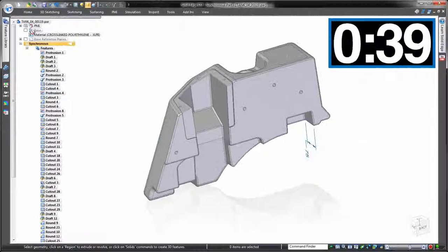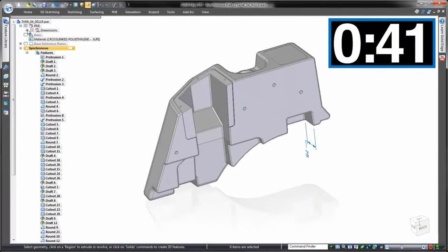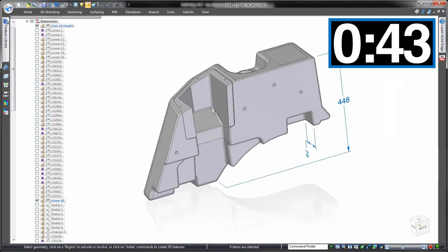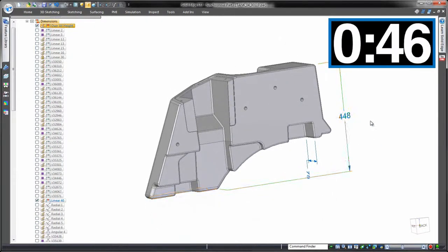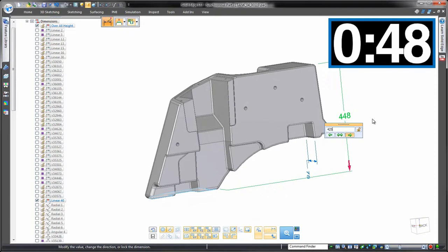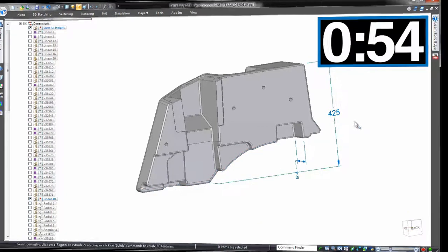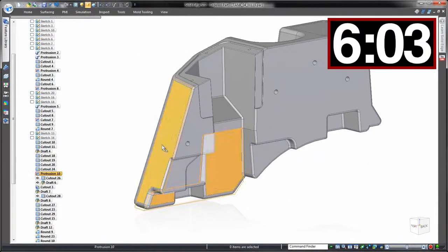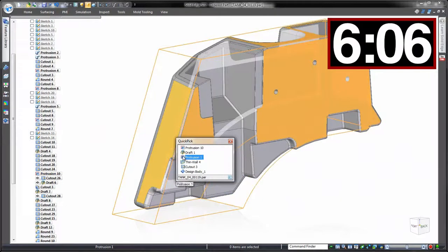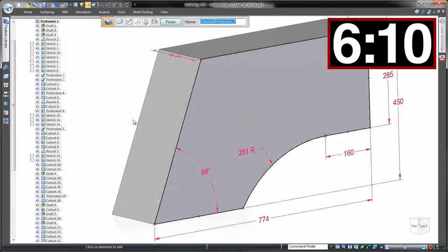Using synchronous technology for that same change, we can make use of any reference dimensions that we placed when we built this as a history-based model, but the difference is they'll actually control the geometry. Choose a dimension, enter the value, and let synchronous technology look after the rest. One last trip into the history-based approach, we need to increase the front angle 15 degrees to compensate for loss of internal volume from those other changes.